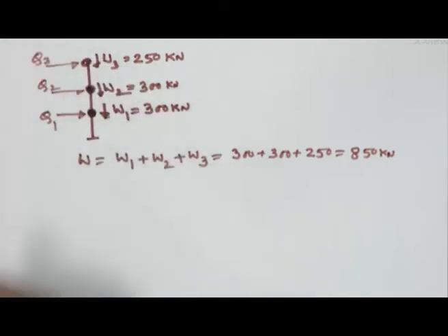As you can see, in the very beginning I have shown you that video where it is moving laterally. So when it is moving laterally, obviously there is a horizontal force, and that force is distributed as Q1, Q2 and Q3. So that is the one we find out here. So, 5.1, 20.4 and 38.25. That particular force we have to calculate. So this is the one we calculate.